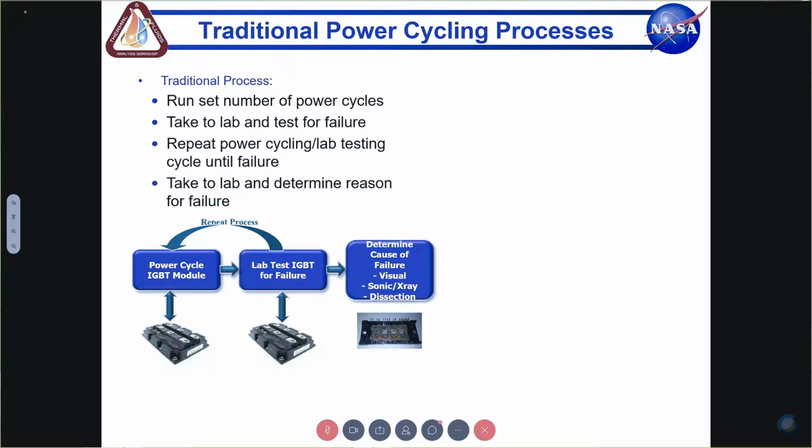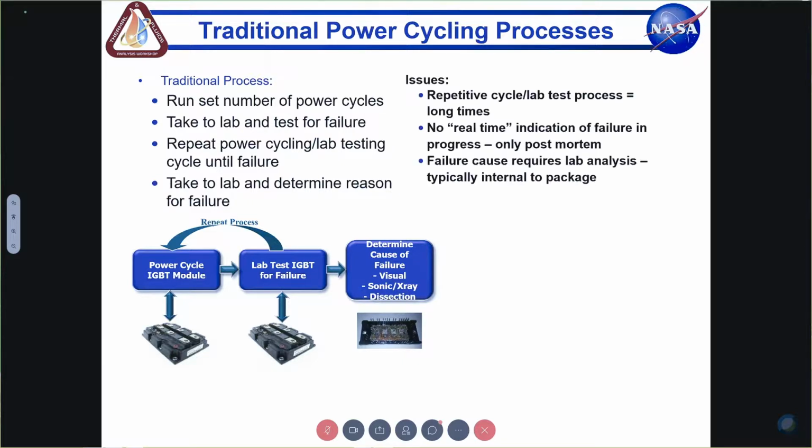After optimization, the optimized simulation model is shown in green. The green and the blue curves, they overlap very well. So typically, if you don't do this, you may miss some of the resistances and you might underestimate your thermal resistances in a system.